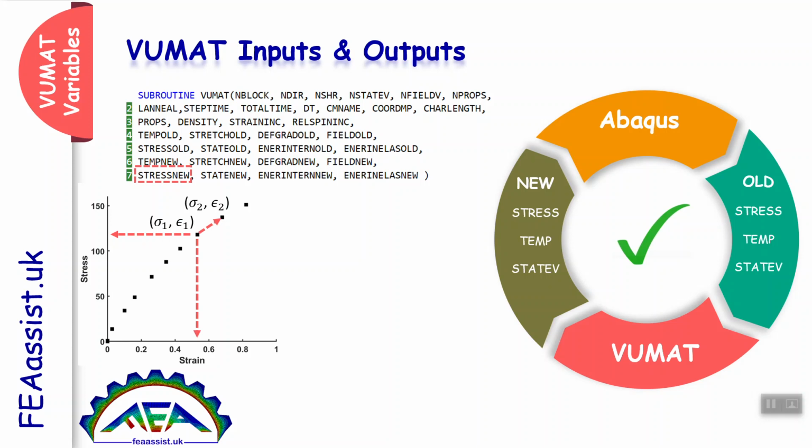In a dynamic way, the strategy is that the new value is the old value plus the derivative function, which is a function of the slope of the diagram and the incremental amount of the strain, as you can see here. For example, in elasticity problems, the slope is the elastic modulus or elasticity stiffness matrix. Well understanding all these variables is necessary to write a good VUMAT.